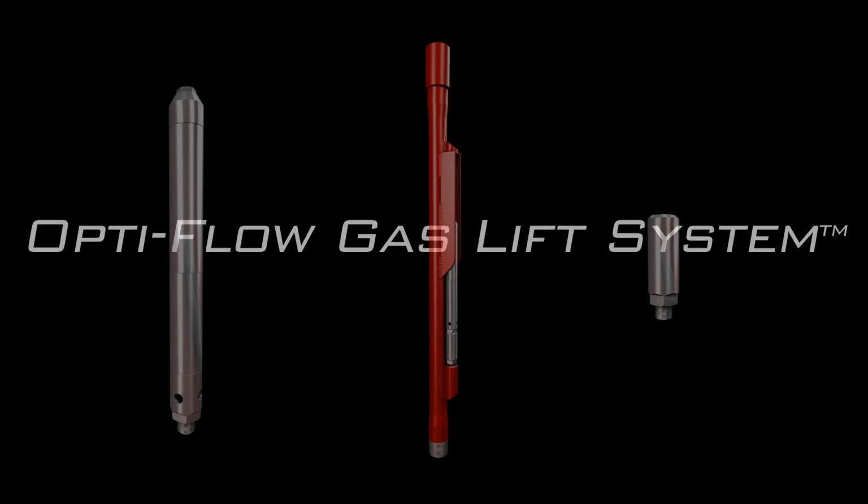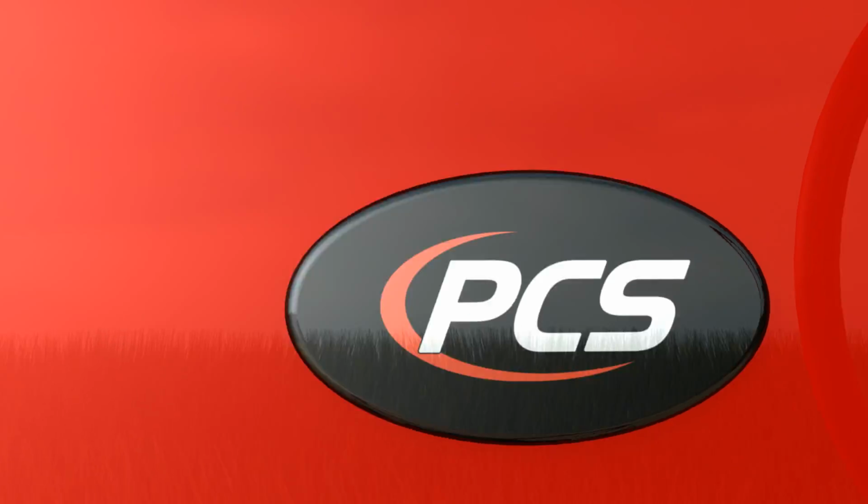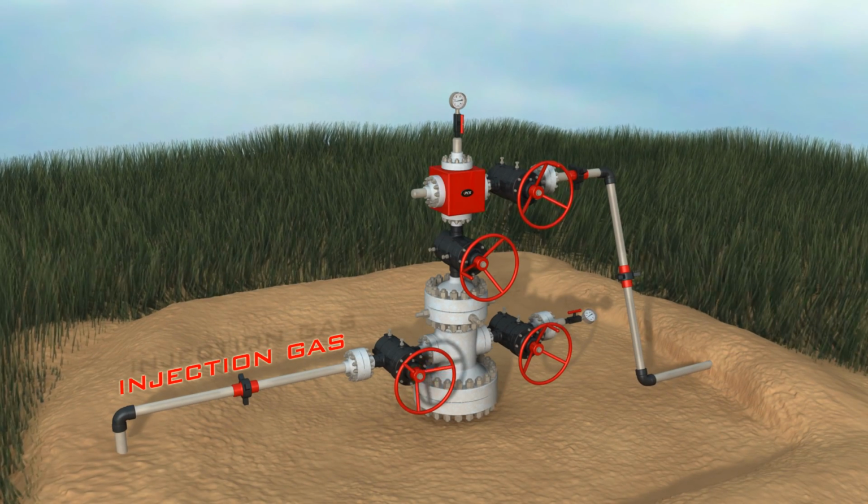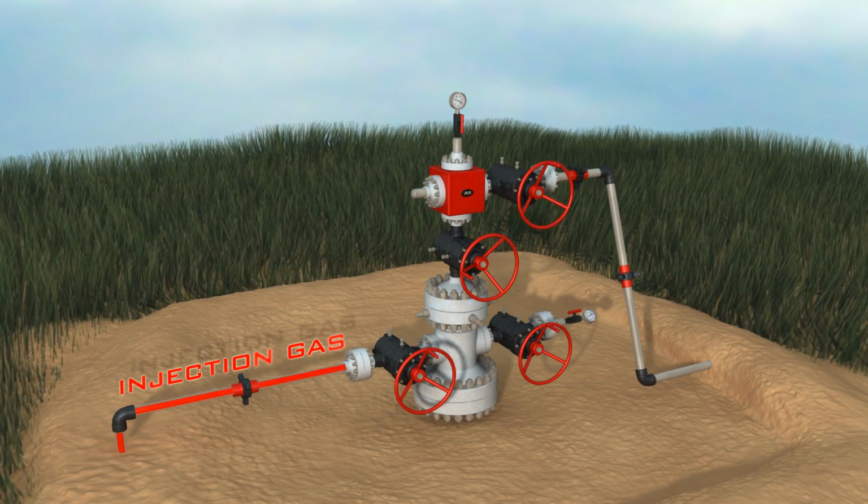The Opti-Flow gas lift system by PCS uses a high-pressure source at the surface to inject gas down the annulus into the tubing. The compressed gas is injected into the production stream through gas lift valves fitted in integral mandrels. The mandrels are installed as part of the tubing string and are positioned at prescribed depths.